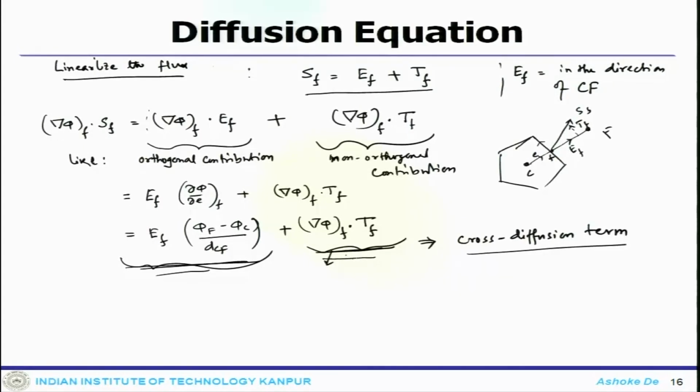That is one of the beauties of the finite volume method: things can be more generic in nature, and higher level things can always be simplified to the lower level one. Though we started from the orthogonal system and moved to a non-orthogonal system, the non-orthogonal system boils down to the orthogonal one for a special case.